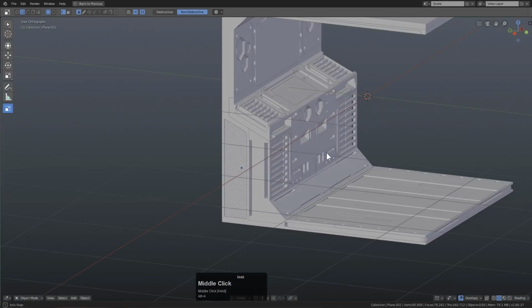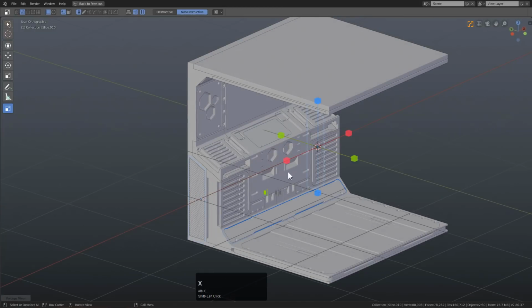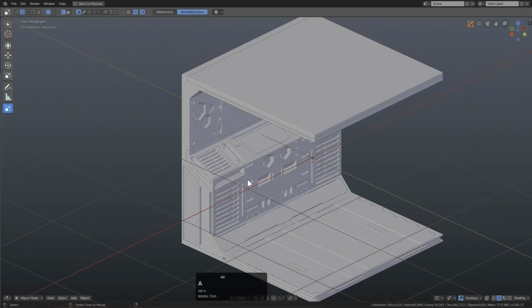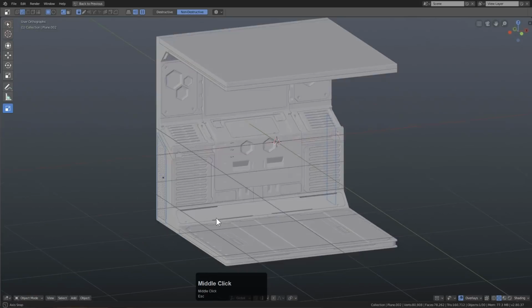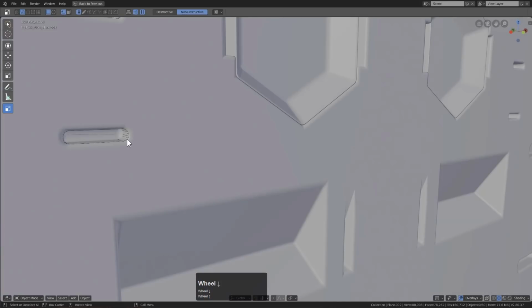We're just going to mirror that to the other side using the 2 object mirror. If you select one object, select another object, and press Alt X, your icons will be green. And that means that you have 2 objects selected. So if your mirror tool doesn't look like this, that means you have 1 object selected. Just a little FYI. This shape here, you know where it belongs. It belongs in cutters.